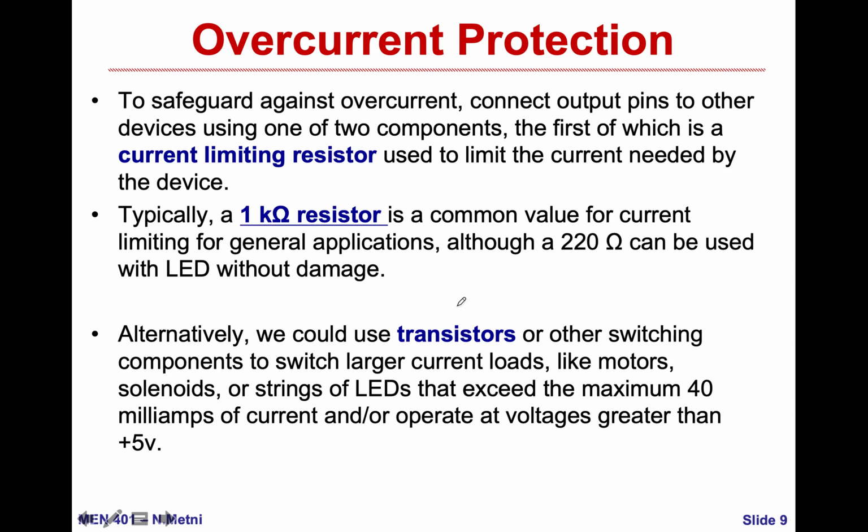We can use transistors in a way that this is the pin, and this is the transistor, okay? I know that here I can connect anything because I'm taking the current from here to here, and the microcontroller is only controlling the base current. This is a very, very important application in mechatronics systems, where the transistor is used as a switch, and we saw this many times during the semester, plus during our milestones.